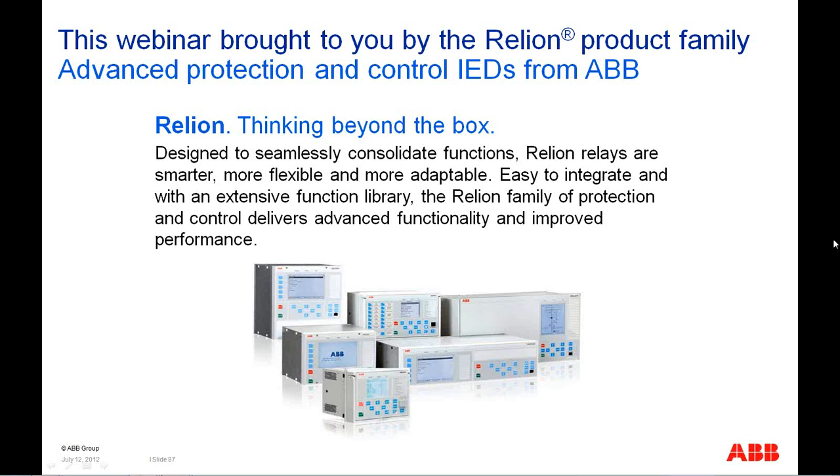What's the rule of thumb to prevent the saturation of CTs in terms of CT voltage ratings? I guess I don't know a rule of thumb to prevent saturation of CTs. It's a more complicated problem than just having a rule of thumb. I would refer you to the CT saturation calculator that we have on our PSRC website, and you can put your CT information and your system information in there. You can determine if the CT is adequate for your application.